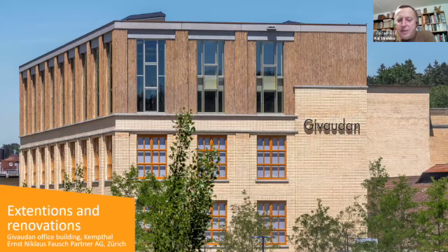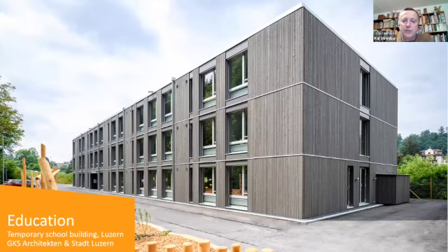Another example is extensions and renovations. In Switzerland, a big topic is densification of cities. And if you densify a city, wood is an extremely valuable material because it's a light material and you can build on top of existing buildings, like you can do extensions, something you cannot so easily do in concrete, because you have to make stronger the foundations and the structure of the building very often. So wood is a light material and it's very easy to do extensions with it. And I think this will be a very big topic also in the near future.